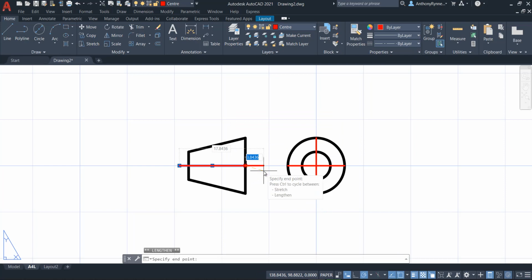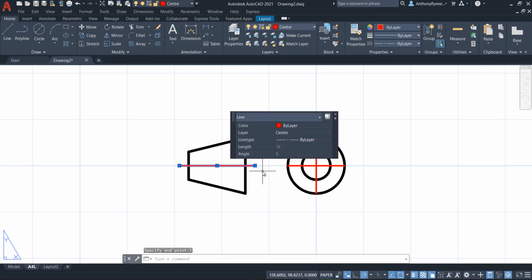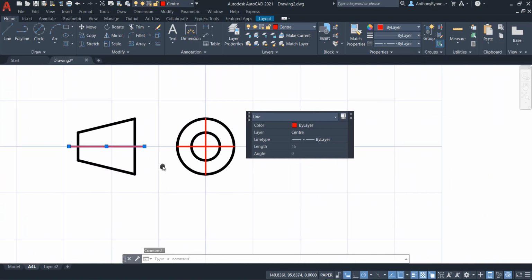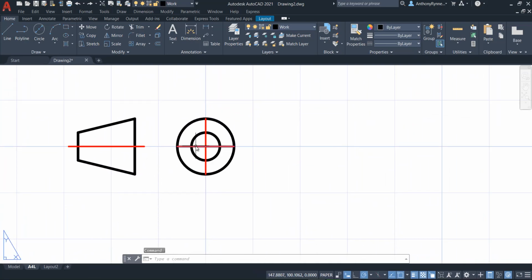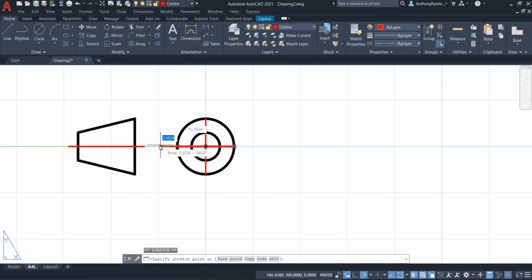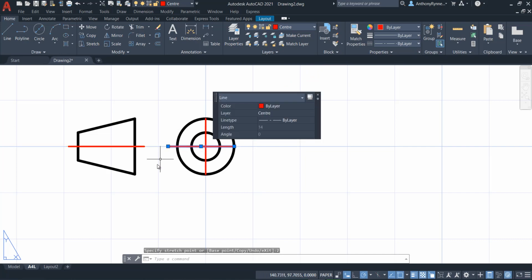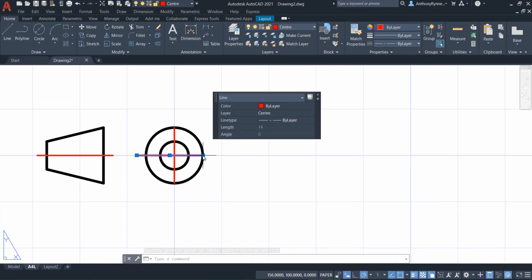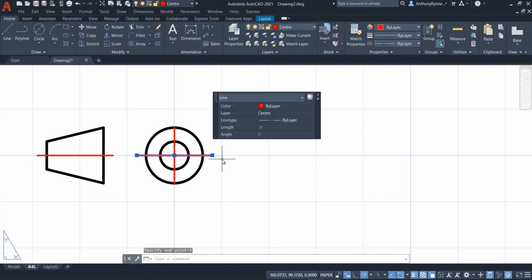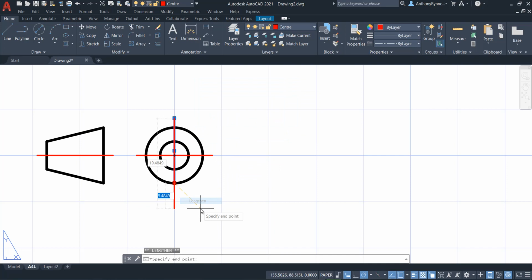So I'm just using lengthen, and we'll lengthen that out 2 mil there. So this line now, if you click on it, is 16 millimeters long. Let's click on this and do the same here. So I could also use stretch. You have to be careful when you're using stretch because you can drag it off the horizontal. So we want to stretch it out there 2 mil. Line is now 14 millimeters long. So the safer option may be here just to use lengthen, but either will work. Just drag it.